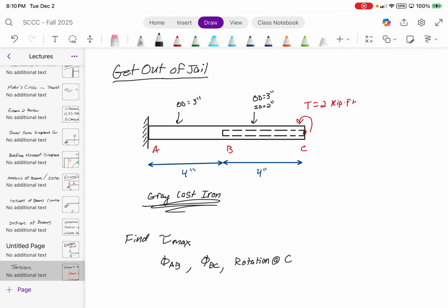They are in radians, I think. I just think you're forgetting to multiply it by that 180 over pi conversion. So the max shear stress I think is right, but for the total rotation at C, look back at the beginning of the semester notes. How did we find the change in position due to elongation or compression? What would we need to do?